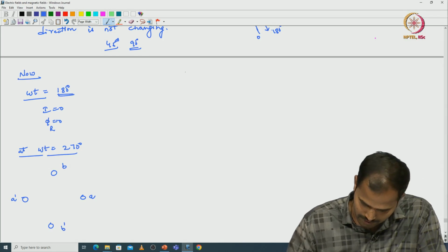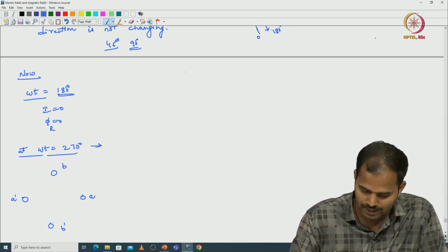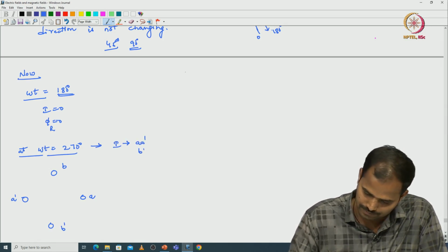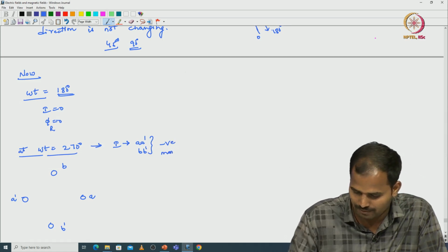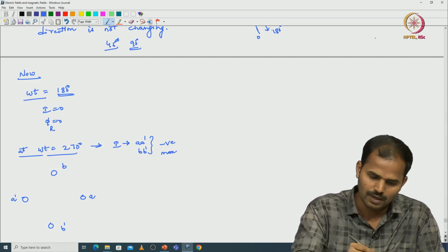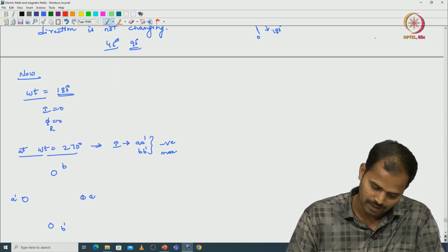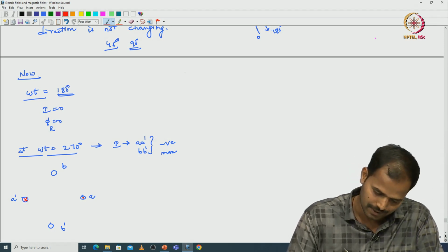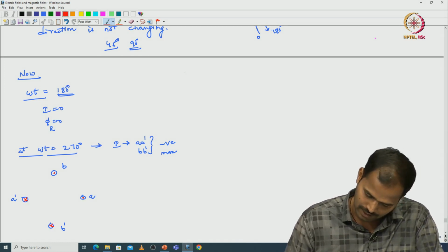These are the conductors. At omega t equals 270 degrees, the current to the coils A dash and B dash is negative and at maximum value. Negative means at A the current is leaving, at the terminal A dash the current is entering, and similarly for B also current is leaving and at B dash current is entering.